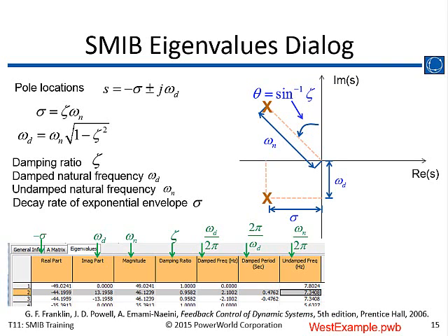This is telling you what's called the small signal stability of that generator. Small signal just means if you give the generator a little kick, how will it respond? The eigenvalues tell how it will respond. The response has a frequency value and a real component. The frequency value is associated with the imaginary number. The real number tells you whether it's decaying with time or growing with time.